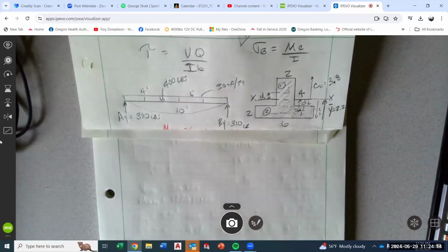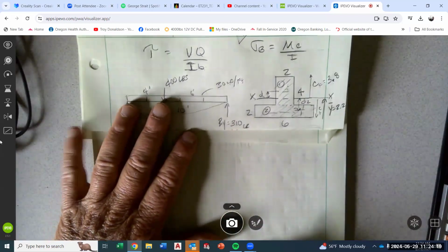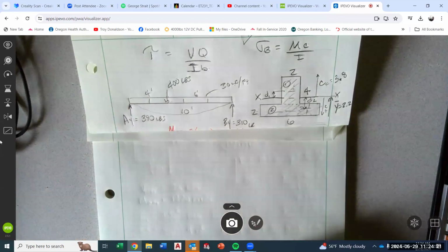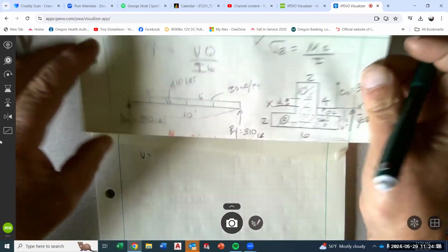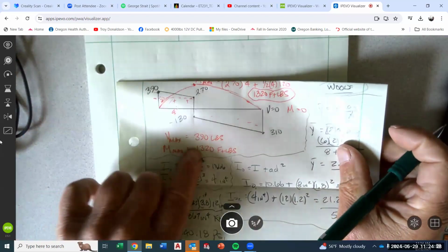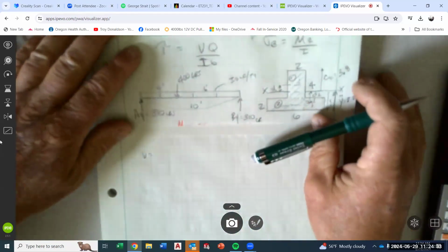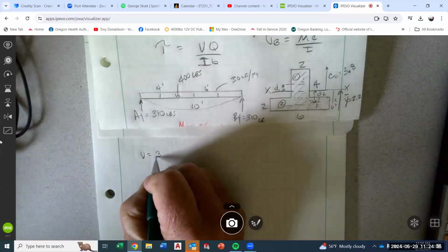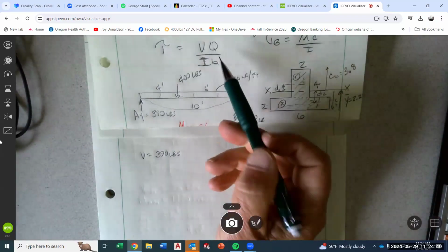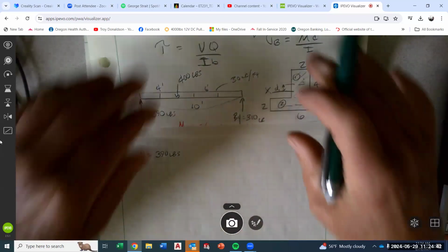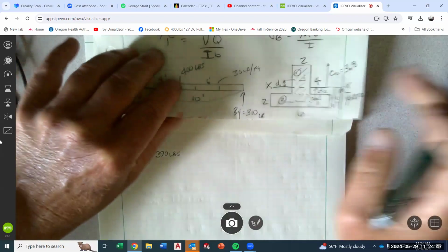When you go for shear stress, it's this VQ over IB, right? So let's just talk about each one individually. We'll do the simple ones. V is from the diagrams. So V from the diagram gave us 390. We know we calculated I at 57,867.